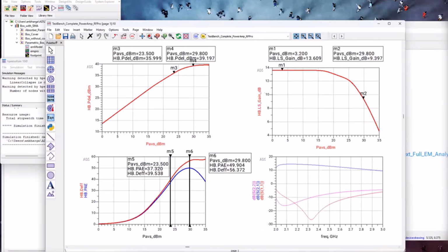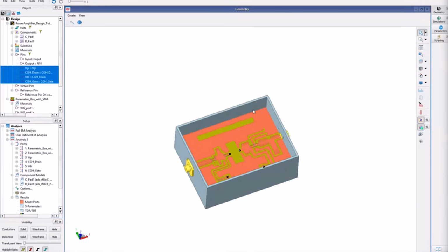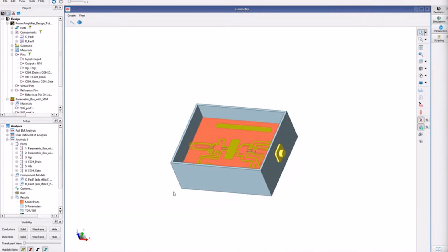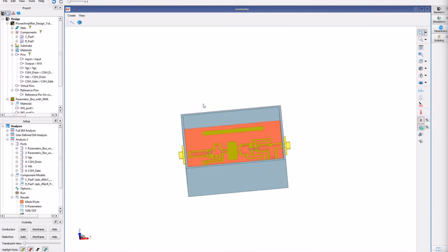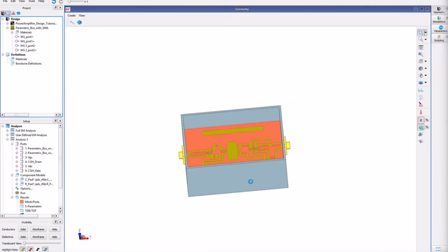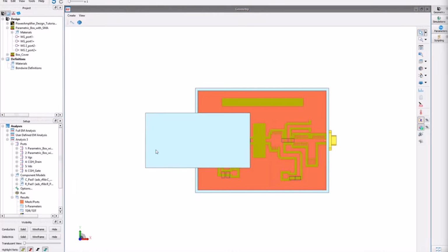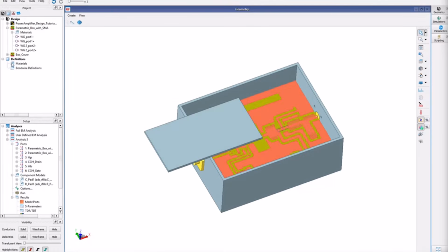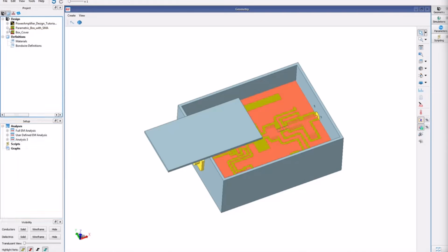Now, funny things happen when you have cover mounted on top of this box, isn't it? Because that's when the cavity gets formed. Right now, you're only accounting for SMA mismatch, SMA transition, this metallic boundary, but it's open air. So in the library I also have a cover plate model separately. And in here, box cover, insert OK. And now I have a box cover. Right? Same like earlier, I can go ahead and put this cover wherever I want and close the cover, run simulation.